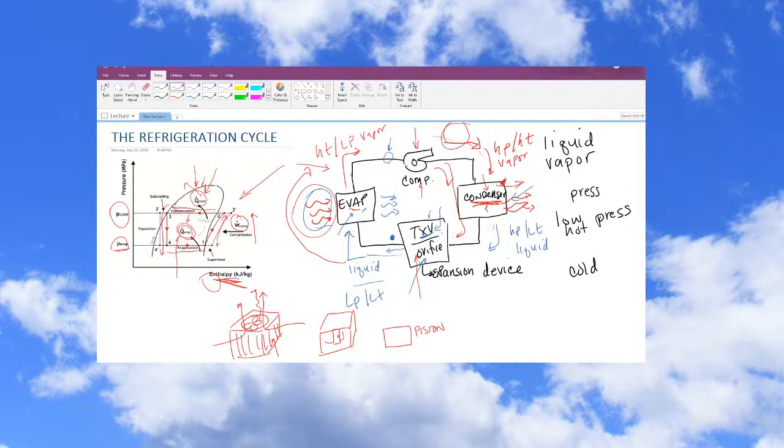So, but you gotta look past that fan, because that fan is only a small part of the whole function. It's just moving the air across your condenser coils, just like when you're driving your car down the road, the speed of the car and the air is moving through your condenser on the road. That's what that little fan's doing.